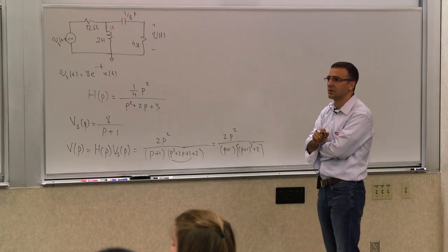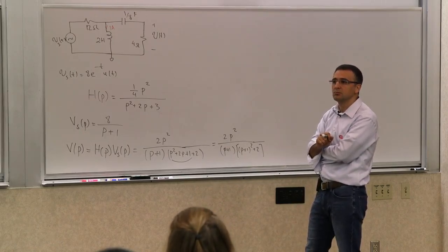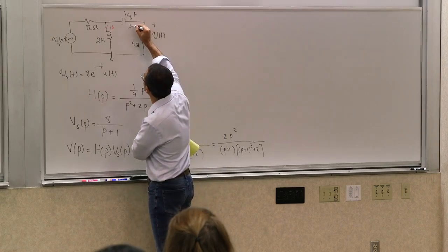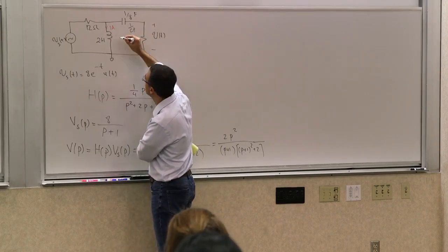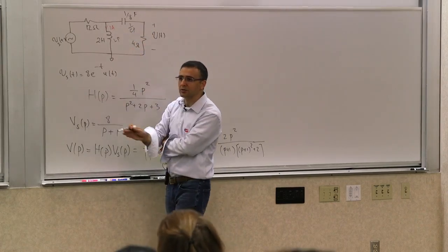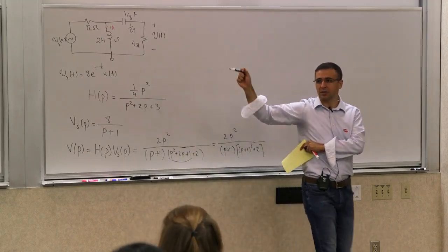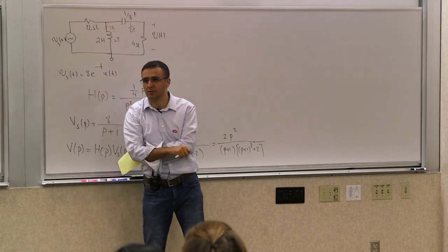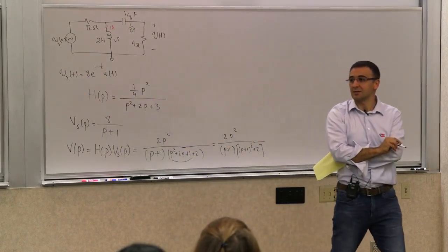Looking at resistances, but solving it down to what is the impedance seen by that. Exactly. So I treated this as 1 over Cp, and I treated it as Lp, and treated them like resistors. It's just the ratio of this voltage to that voltage if you had these 4 resistors, which we now call impedances.